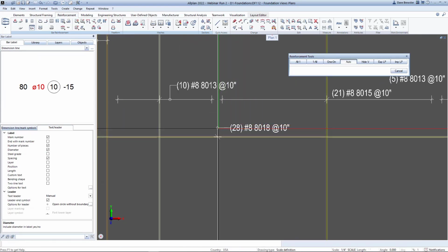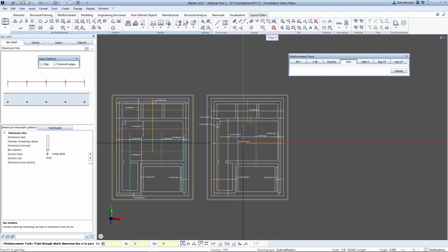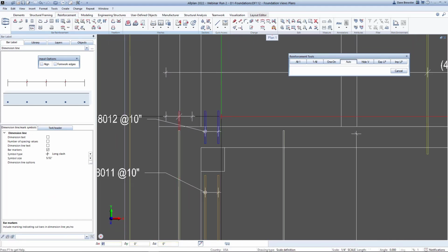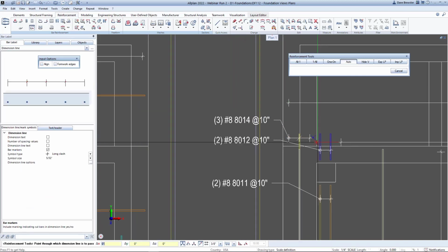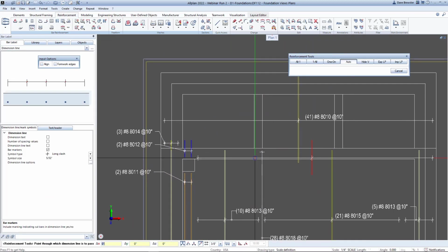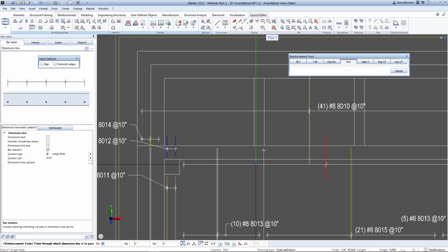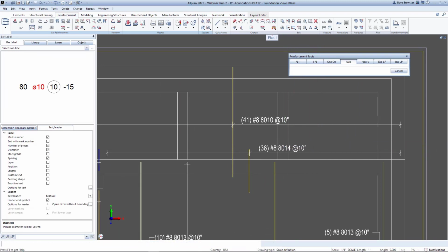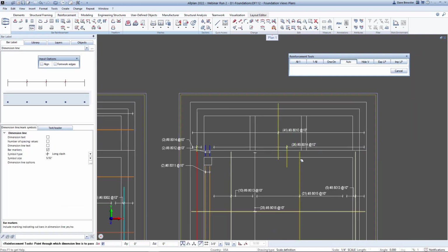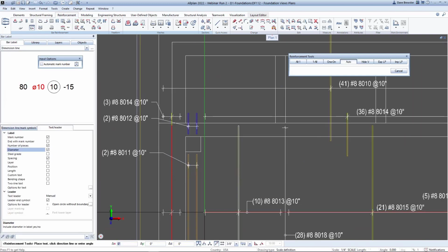The text height has already been predefined here. I believe it's set about 1/8 inch high. Each drawing file has what we call a view scale. If you look down at the very bottom of the line, it's a 1/4 inch scale. That means if I put this particular drawing on a sheet at a 1/4 inch scale, my text and spacing will look exactly like this. So we have the ability to define that. We don't have to do it after the fact. We can change it and see what it looks like. This was already preset.